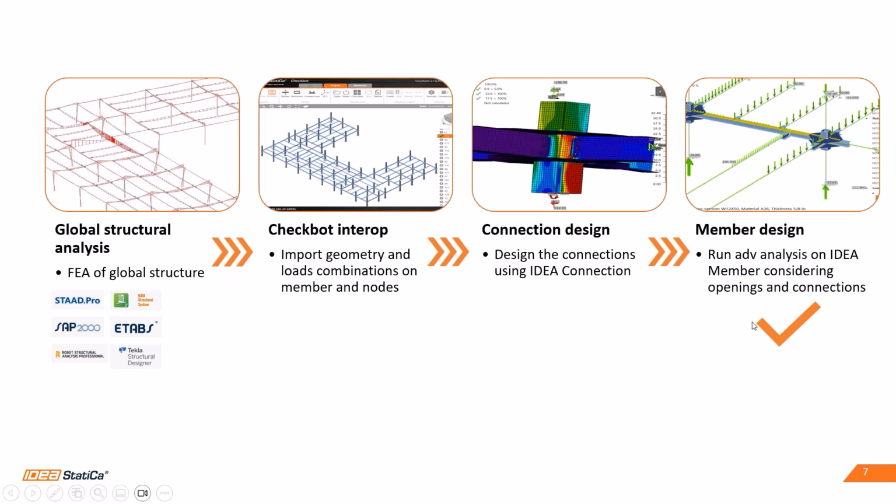Now let me show you what is the proposed process. First of all, you can use IDEA Member in a standalone way. So you will open IDEA StatiCa, and then you click over the Member icon, and then from there you can start from scratch. But the hard part of that is that you need to input all the results from your FEA, or you will need to input all the loads into that member, right? So this is why I like to show you Member using other applications and using our links.